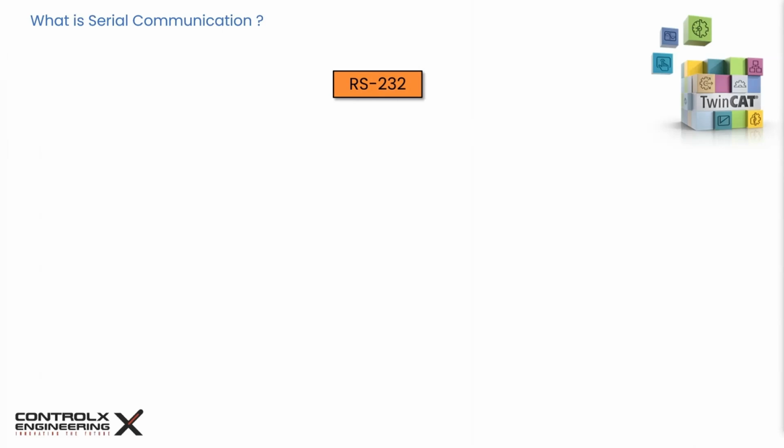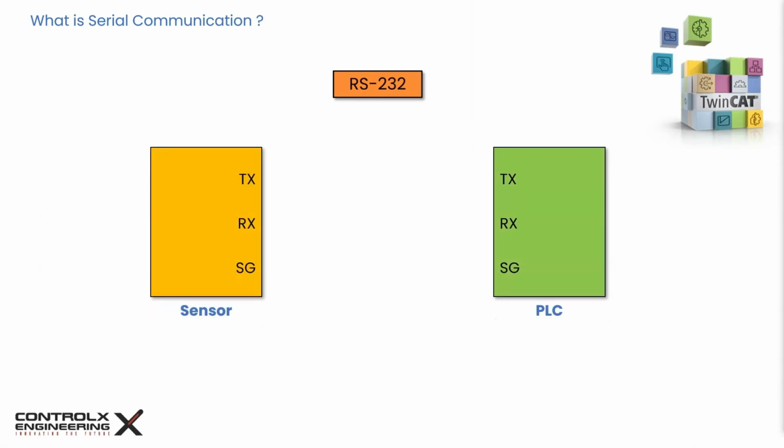RS-232 is a single-ended standard between a transmitter and a receiver. Usually the communication is bidirectional, so both devices can transmit and receive data. I mentioned that RS-232 is single-ended. This means that the data is transmitted as a voltage difference between a single signal wire and a common reference point, typically ground. Thus, at a minimum, at least 3 wires are required between the two devices.